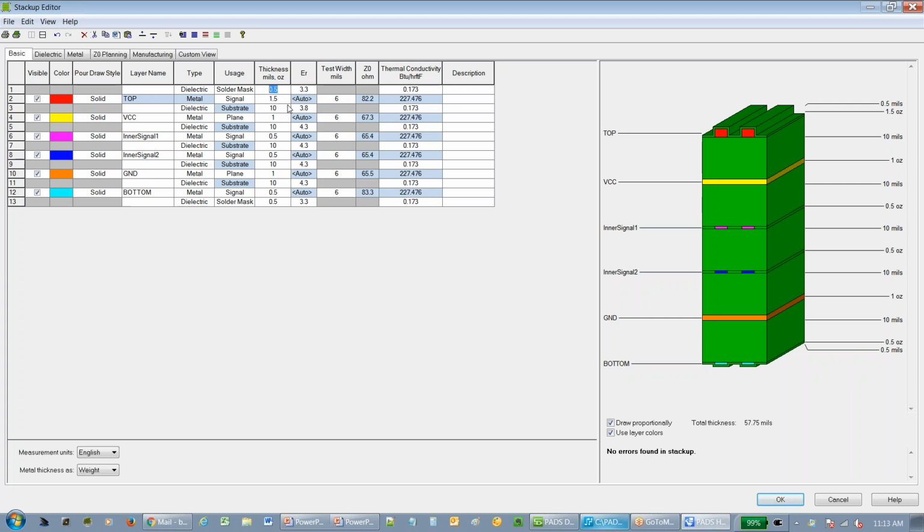Solder mask is typically about 1 mil thick on the board. Average dielectric constants on those is around 3.8. And you can see again how that affects the impedance of the trace. Okay, so if you're definitely doing any impedance matching, you need to make sure you take that into consideration, and some of those calculators online don't provide that.